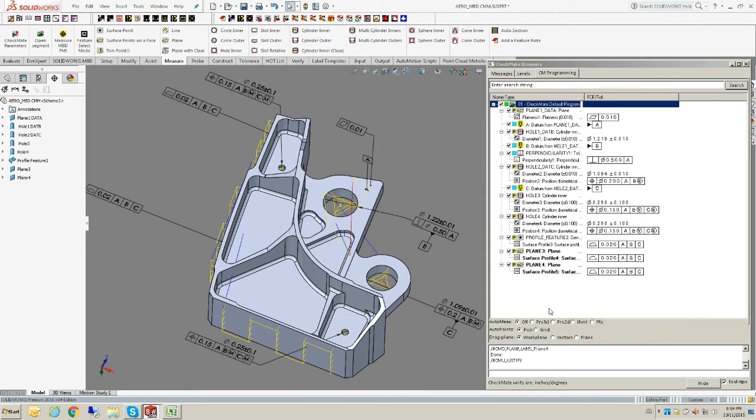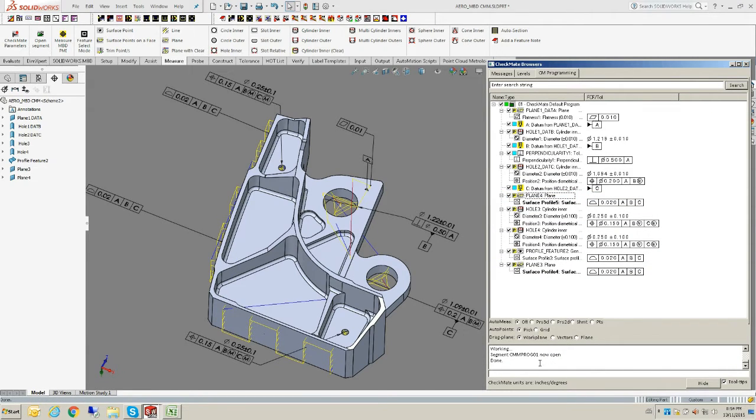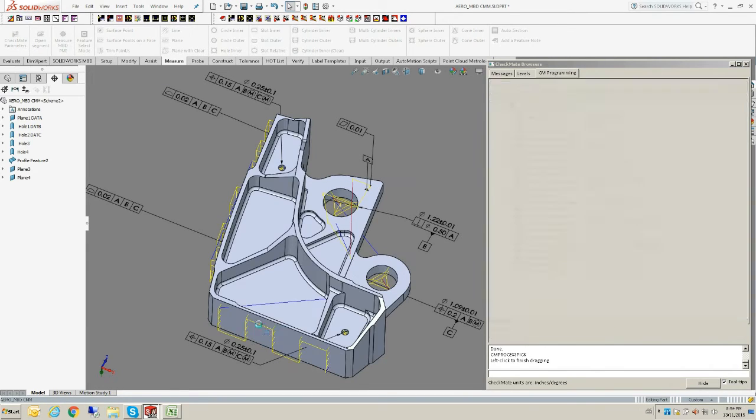The programming browser is Windows-like with folders and fully editable measurement features, and is used as an interface to enhance programming functionality. The order of the program can be edited simply by taking a feature and dragging it up anywhere within the browser. Measurement features also can be moved around on the CAD simply by clicking on them, moving them over a little bit just to fine-tune the program.